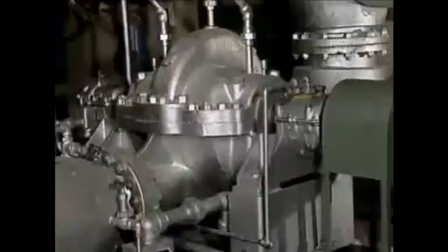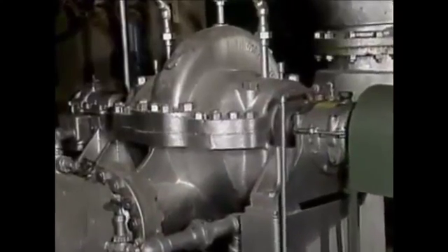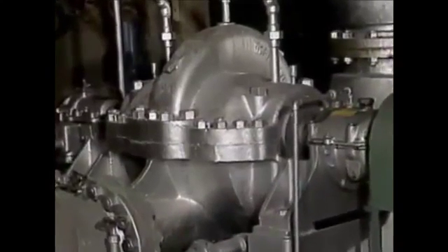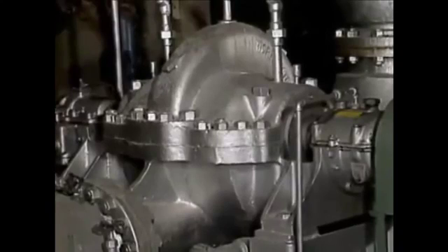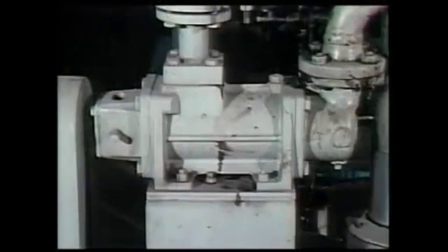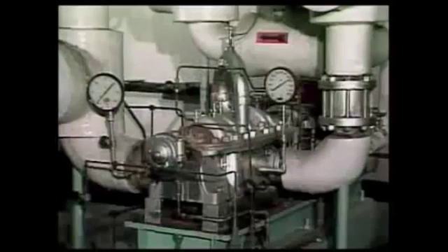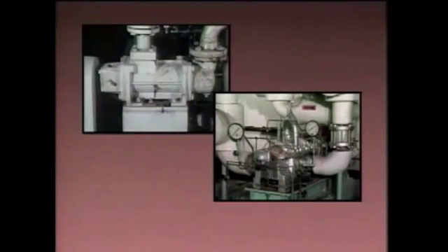To get a better understanding of how a fluid system is structured, let's look at how the requirements of a liquid system are met. In a liquid system, the energy that's needed to perform a task is often supplied by a pump. A pump adds energy to the liquid and creates flow. 2 types of pumps commonly found in liquid systems are positive displacement pumps and centrifugal pumps. While these pumps operate differently, they both cause flow by creating a pressure difference in the system.